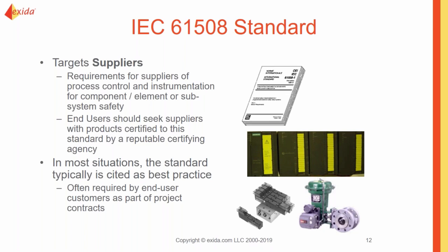In some countries, the standard is becoming more accepted by governments and enforced by law, but I would say in most situations, the standard is just typically cited as best or common engineering practices. It's often going to be required by end users saying, well, we want a SIL rated product. We need a SIL 2 or a SIL 3 SIF. I need a third party certificate, show me.